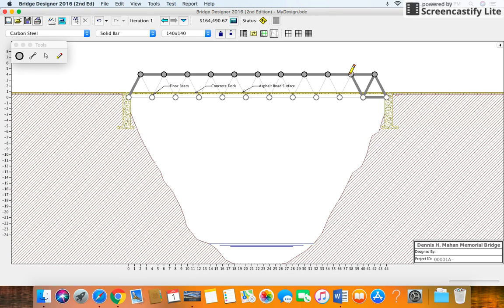Do not add other pieces. Students typically want to add other things that they think are going to be helpful. When you add additional components to the bridge, all you're doing is adding weight to the bridge, which is going to make it fail faster than what you want it to. Which means it's going to fall into the water and won't be successful.